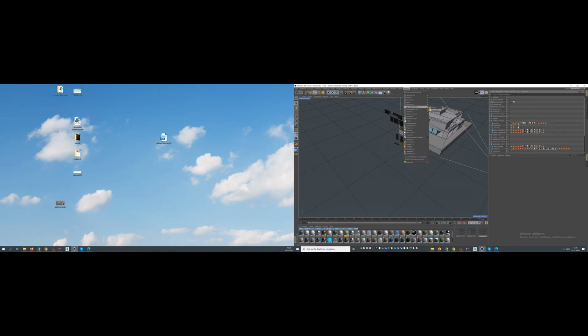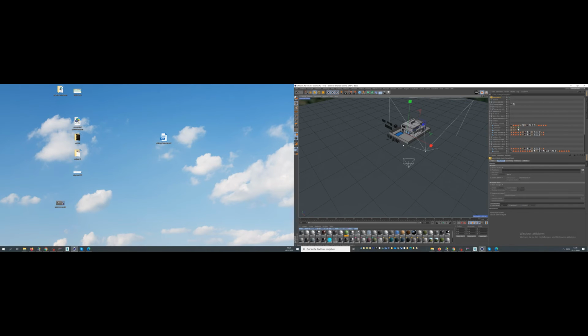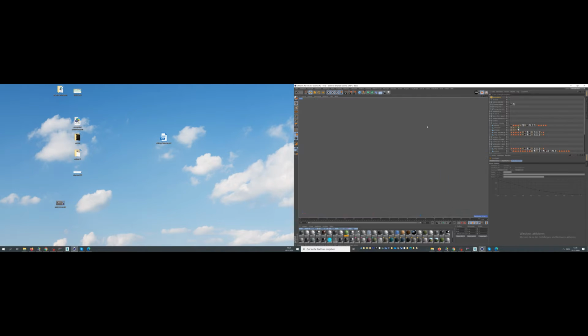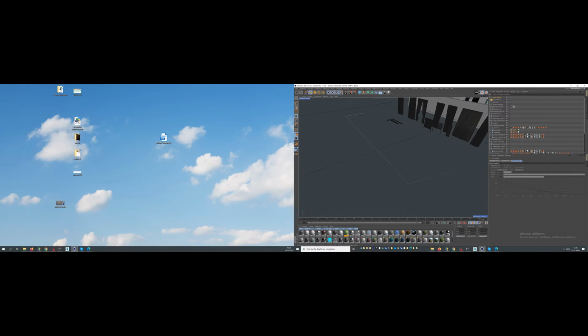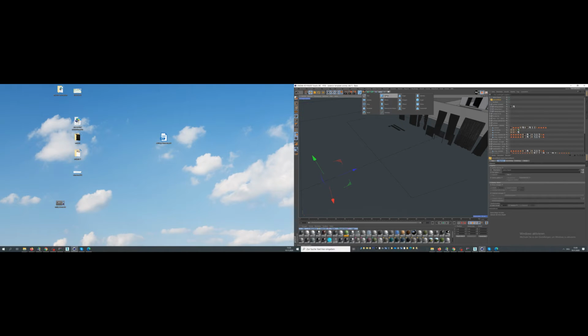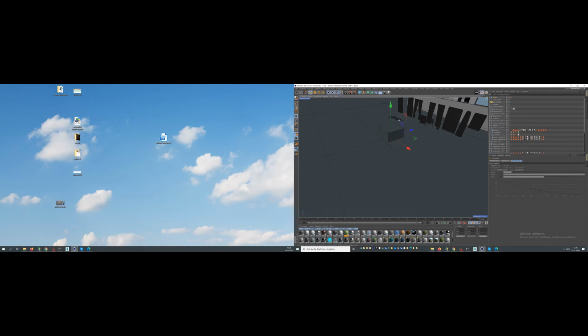It is this Spline Spread plugin. I can use it to spread elements along a spline. Let us make some handrail, for example, some balcony rail. You can build really cool things. You have this spline now and this Spline Spread. You take this buff spline here and can now distribute, if you want to build, for example, some handrail. Now only convert the cube with C.